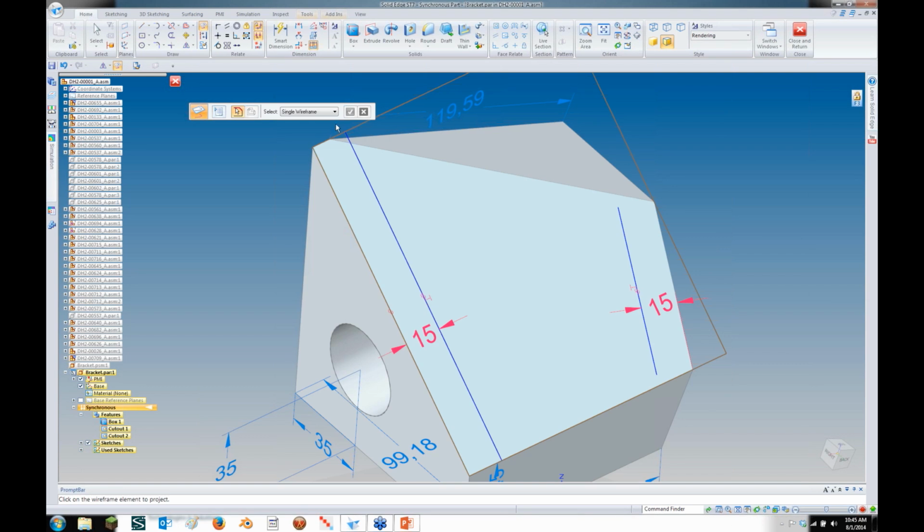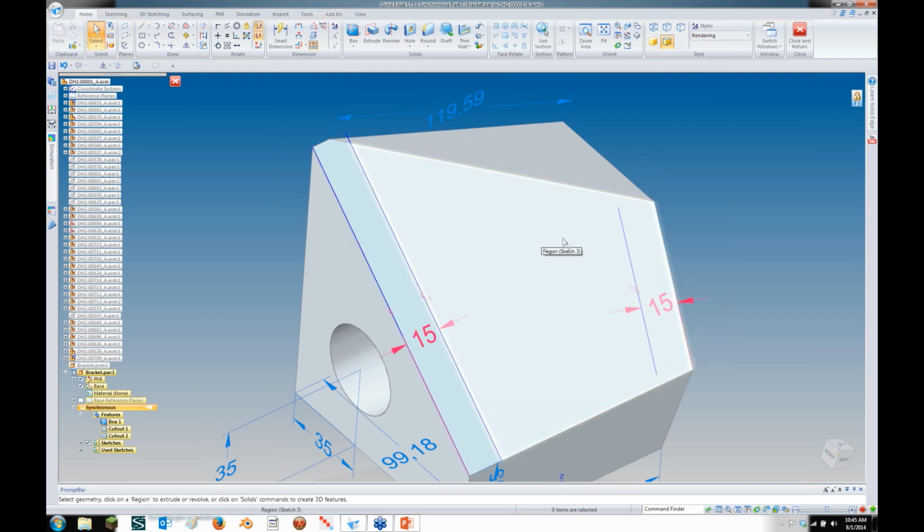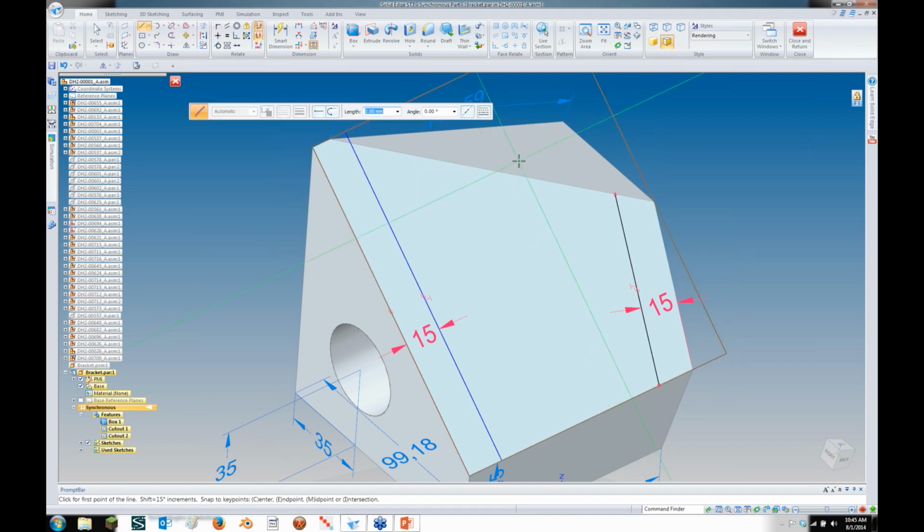All right. You notice we have regions, as we call them here, but this sketch didn't go all the way to the top. So with the same 2D sketching that you would have in any other sketch, we're going to use connect points to connect it to its respective edges. The last thing you need to do is draw a line. We're going to use this top surface to do that, and I'm going to use the key point that I just created, and draw a straight line there.